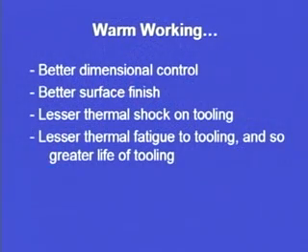With warm working, as I have already mentioned, better dimensional control is there, and better surface finish is obtained. Lesser thermal shock on tooling. Thermal shock is basically what happens whenever the tooling comes in contact with a workpiece at an elevated temperature, so some kind of thermal shock may take place. Here, as the temperatures are less, the thermal shock on tooling is also comparatively less.